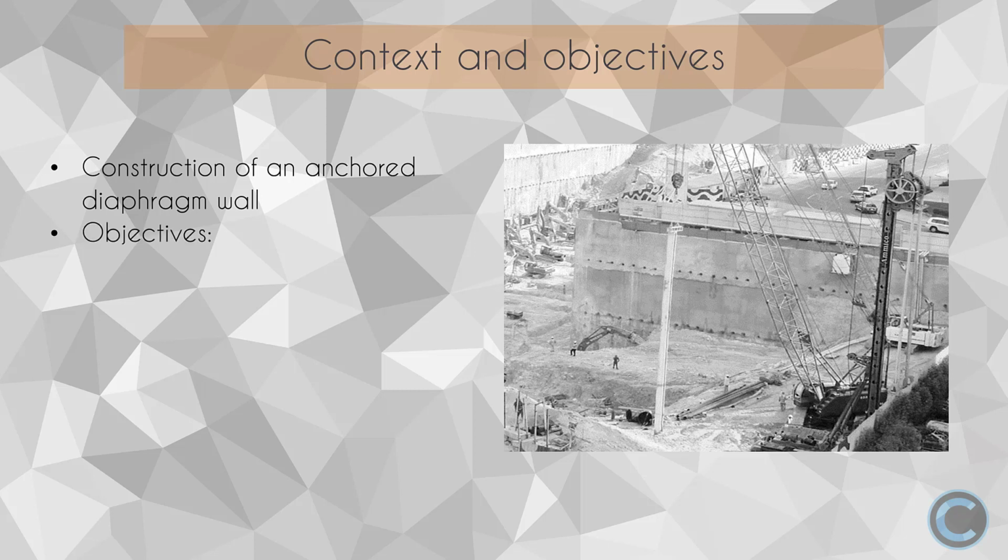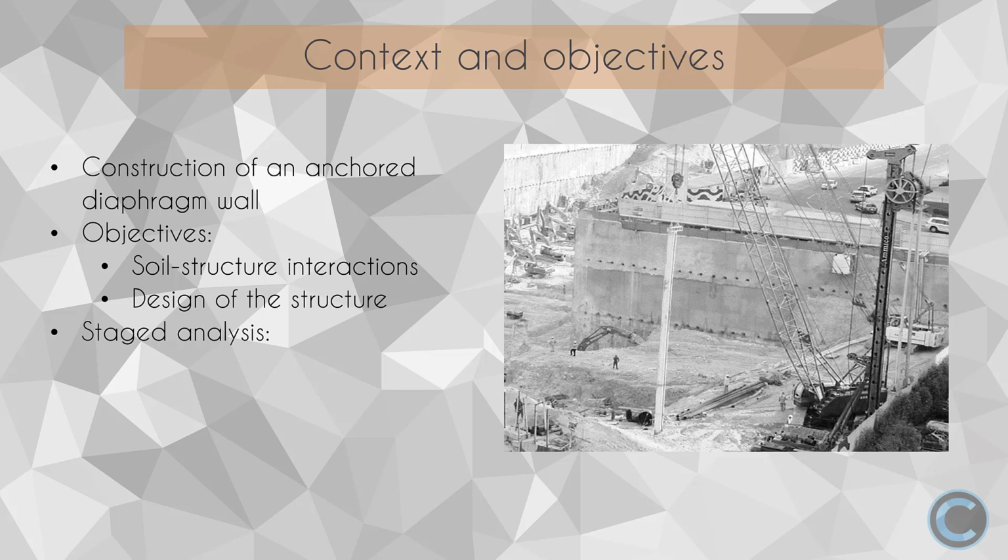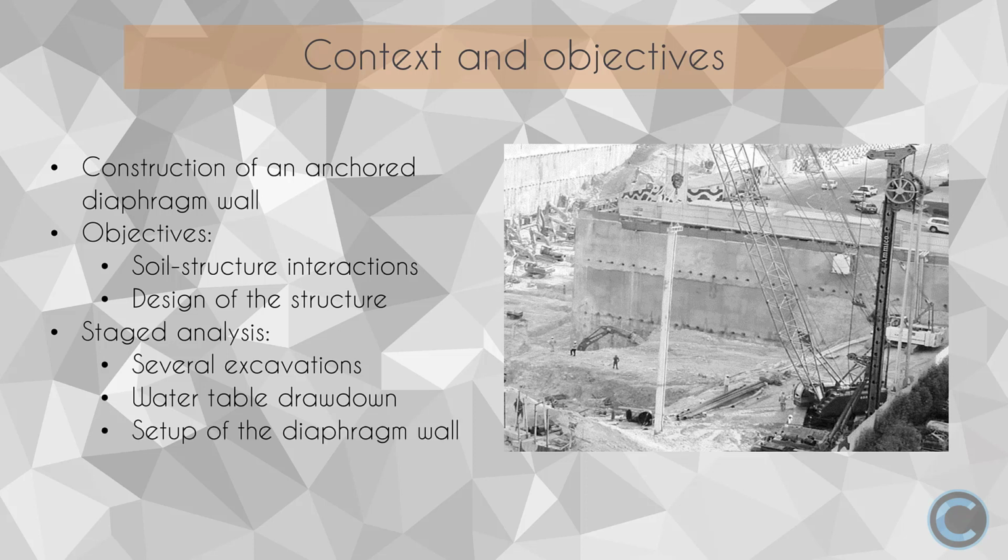Among them is the accurate modeling of the soil structure interactions by using an appropriate soil constitutive model, and the design of the structure by calculating the design efforts in the structural elements. The FEA model will also allow us to represent the work sequences by editing the several excavations, the variations of the water table level, and the setup of the diaphragm wall and the anchor layers.